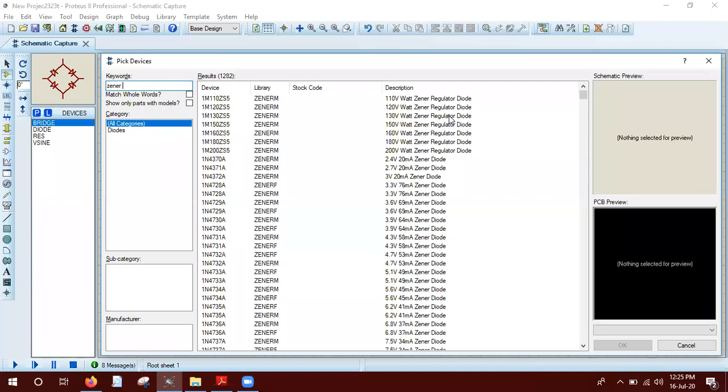So one is the Zener voltage, another one is the maximum current that the diode can withstand or allow to flow. Because if you cross that current level, the diode will be destroyed internally. You will probably not understand it, but it will be destroyed internally. It will not act properly.